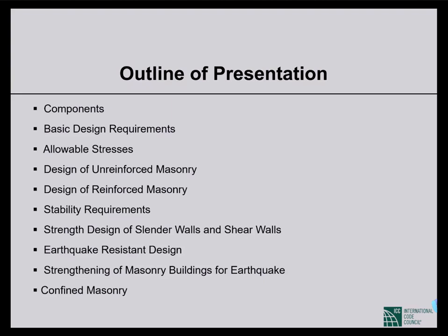So at each lintel level and roof level, we have to provide bands. That's according to BNBC 2020. But there are other publications where we should also provide bands at sill level too. So for the time being, if we just follow the BNBC, at the roof level and lintel level we have to provide bands.